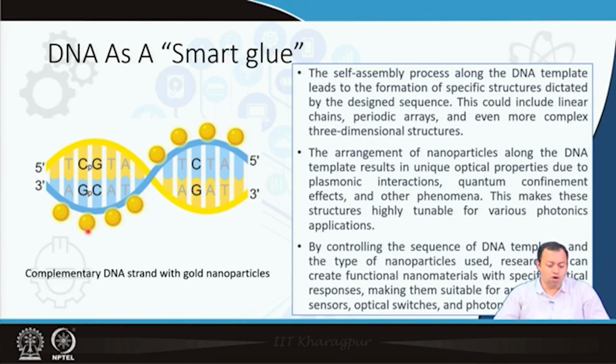So, you just cover one of them with some amount of a biomolecule, something just attaching to it, the resonance of the entire structure will get disturbed, because previously they were identical to one another. Now, one of them is non-identical, i.e., you have introduced a defect. So, there is a small red shift, and that could be utilized to detect the presence or absence of any particular molecular species, meaning you are going into so called single molecule detection.